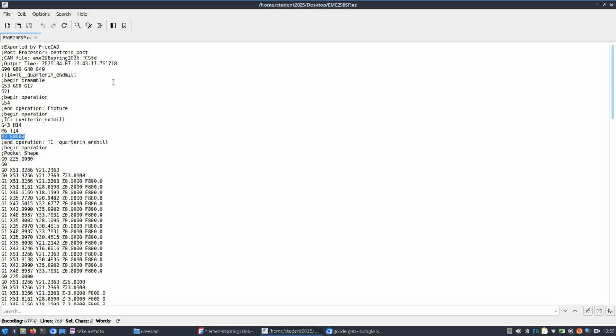Some people, when they're going to design, they sketch on X and Z. So when you come here, your CNC thinks that your piece is like this. It's not going to work, right? So this is a good practice when you create a sketch on X and Y. Put the coordinate right there. What else? Change to CNC small parts, right? On the dimensions here.